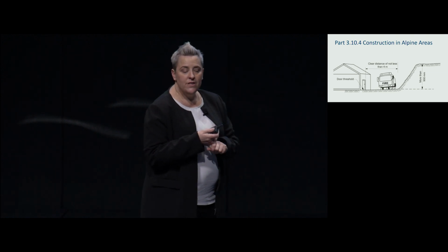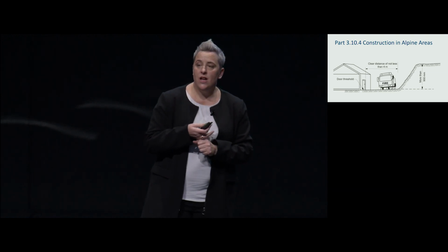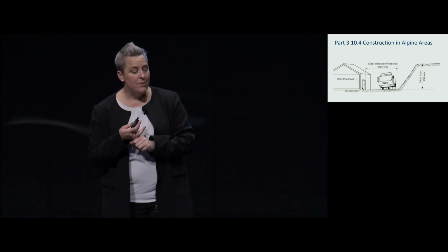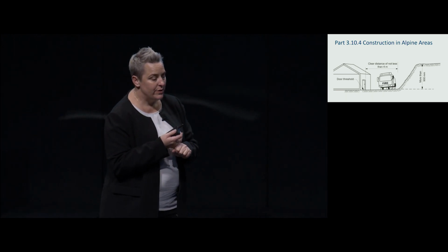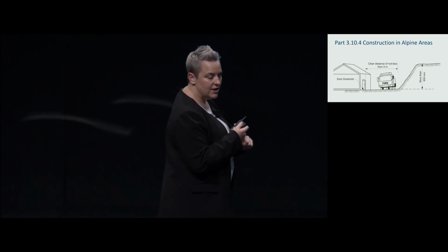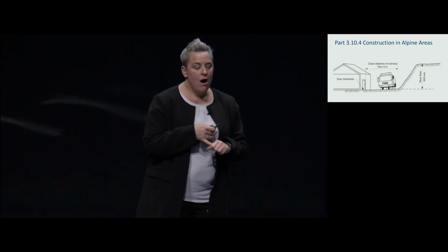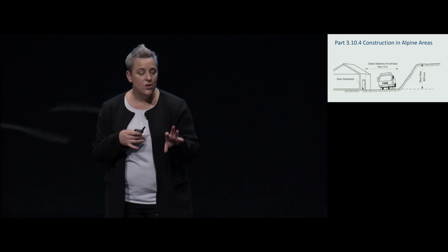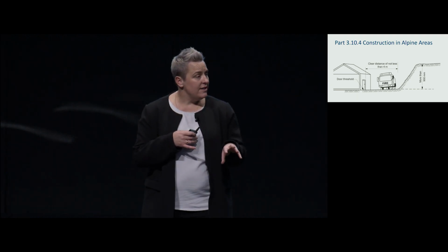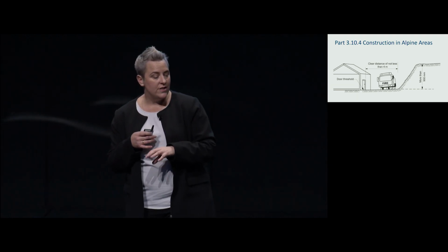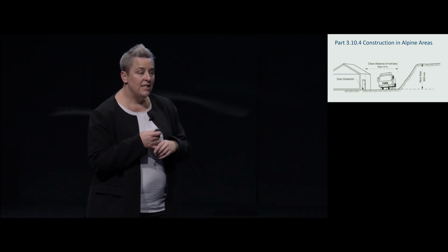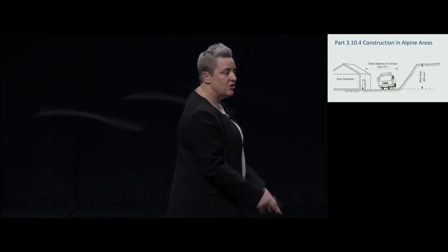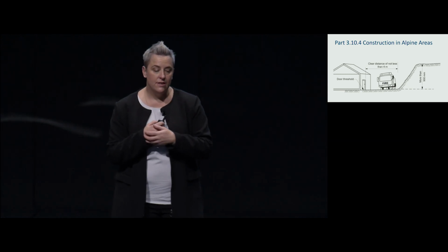The signage requirements have also been amended to apply to only Class 1B buildings, where previously it applied to any Class 1 building, so that's a good change and clarification. The requirements regarding external trafficable surfaces have been rewritten, and the floor surface must consist of expanded mesh if it's used as a means of egress. And once again, it's to get that snowfall through so it doesn't impede egress of the occupants.